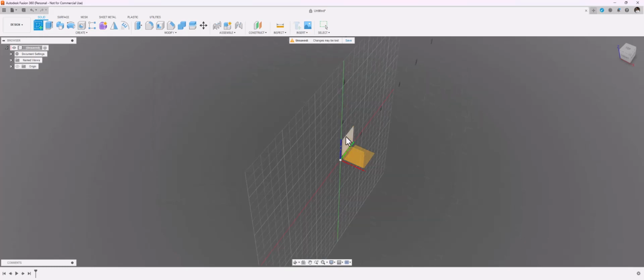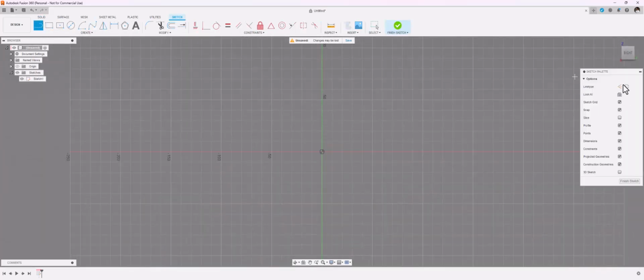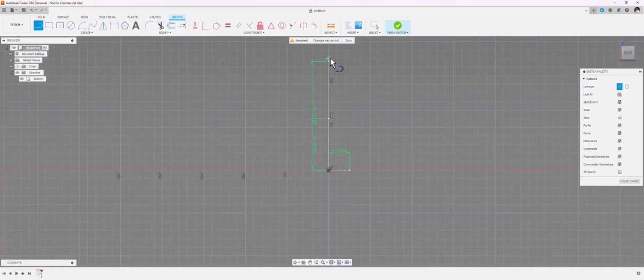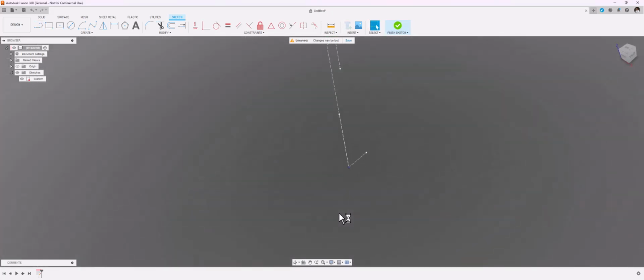What I do now is I create a template sketch using construction lines. It's going to be total height tall. We know that the diameter for the base, we want the radius, so divide by 2. We then know that the cylinder height goes up to there. The neck diameter, we want converting to a radius, neck diameter divided by 2, so that. And we know where that comes down to because we have the neck height. So that's my template for it.